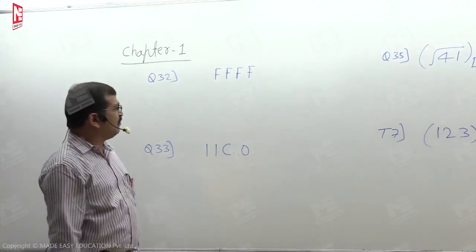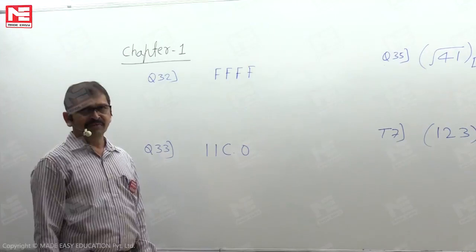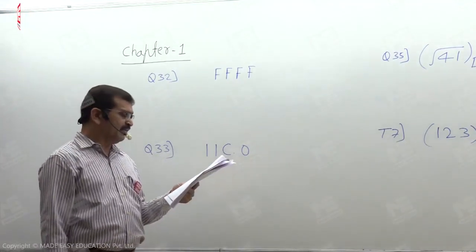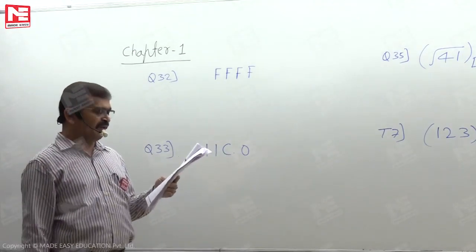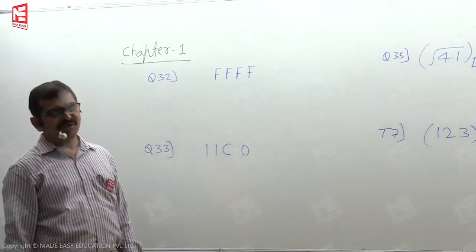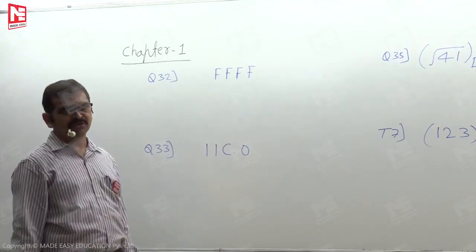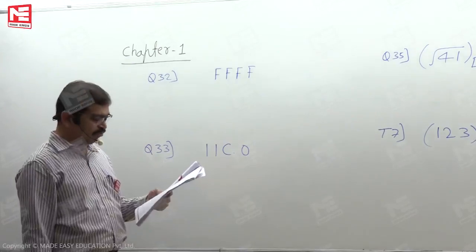Once it is 2's complement form, default design is 2's complement only. Whether it is mentioned or not, it's not the issue. But anyway, in the question it is given 1 sign bit and 15 magnitude bits. If at all such information is not available in the question description, by default the MSB is a sign bit, and the remaining bits will be related with the magnitude. In fact, it is a '93 GATE question paper.